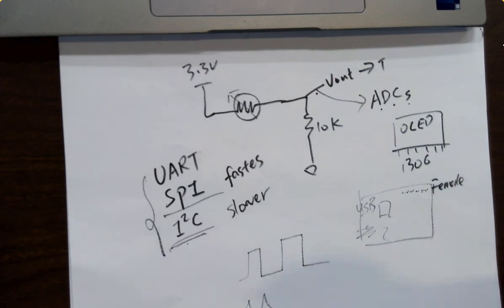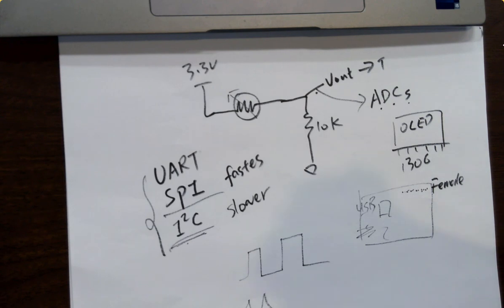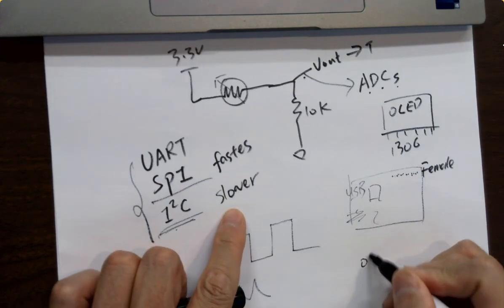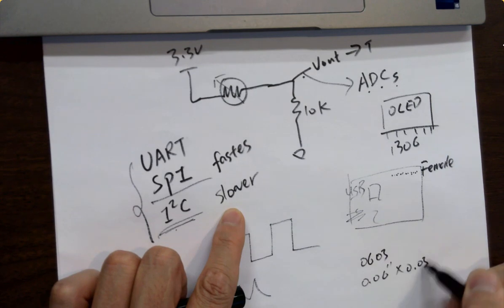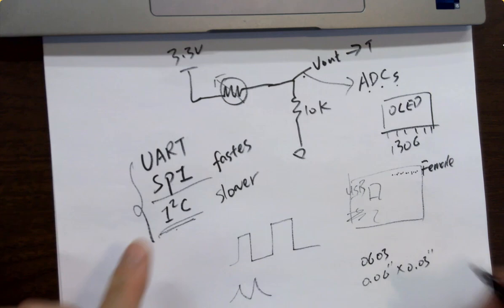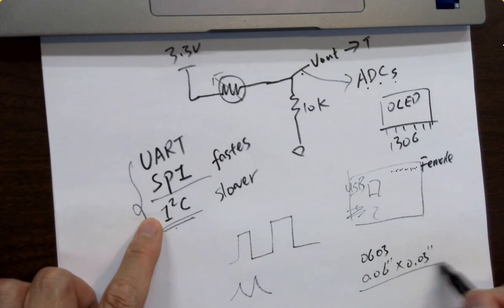Okay. Can we use bigger resistor sizes to make soldering easier? 1206 is already the biggest in my mind. Like I told you, they are actually huge. Even though they are surface mount, they're super easy to solder. The ones I usually use are 0603. 0603 is 0.06 inches by 0.03 inches. That's the smallest one you can handle, but you don't have to use that small.